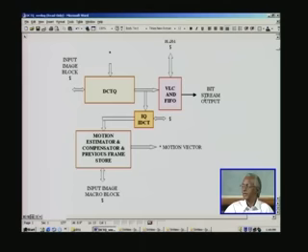At the receiving end you receive this bit stream, and there will be a FIFO there also, and from that we do the inverse operation, namely VLD, D stands for decoder, and get parallel information which is DCTQ equivalent here, and there will be this processor at the receiving end, and that will be processed, and you will get a recovered signal here, and that signal will be the same as this one.